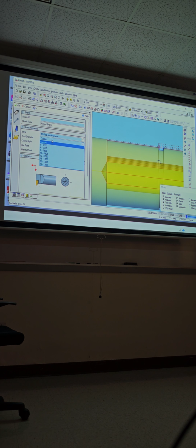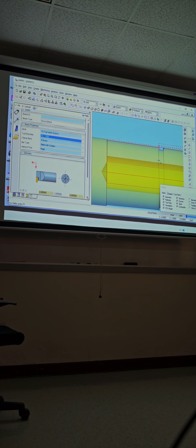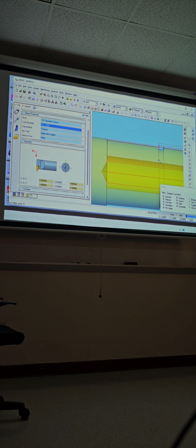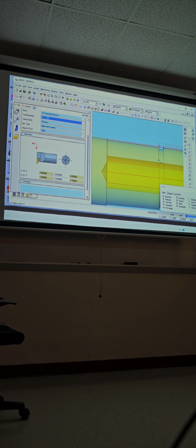2 diameter. So we gotta go inside that hole. Right now it's 1.5 inches. So custom. See, right now I have a 1.5 inch hole. So I can go 1 inch, you know, a little bit bigger tool. Less chatter. Less chatter, that is correct. Can you also do 1.25 inches? You can do 1.25 inches too. Even less chatter. Less chatter, that's right.